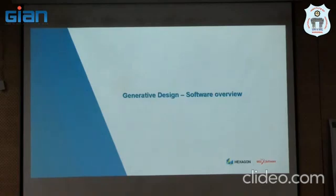Yes, first we have to get a 3D model, because we need the volume. Then we take that into the software, or we can even calculate the volume. Then what is the material required to print that component? Then what will be the material cost and machine cost? Machine cost includes the energy consumption, labor cost and other things. That is how it is calculated.